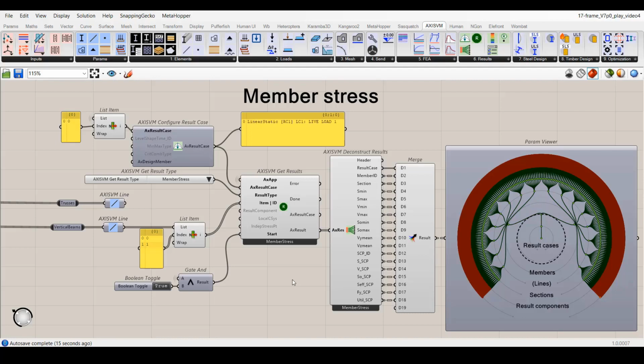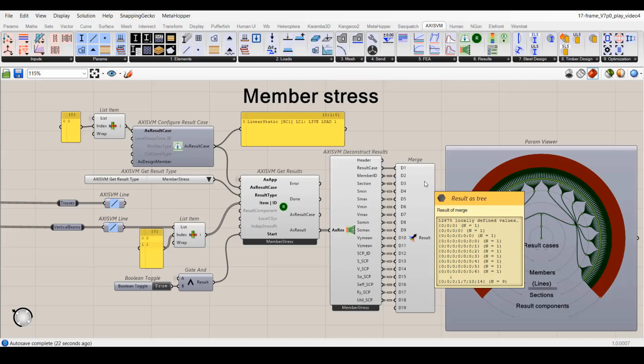I'm going to make further clarification about this later on in this video, but now I rather want to explain that the lines expression is in brackets on the parent viewer because that intermediate path is not really a part of the data tree. You can see that I don't have any branch path with 5 indices, but the 5th index of the section paths is growing from 0 to 7 to group the sections according to the finite element mesh.